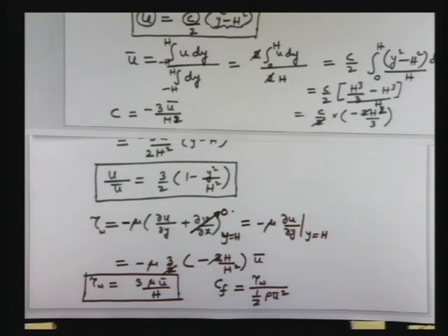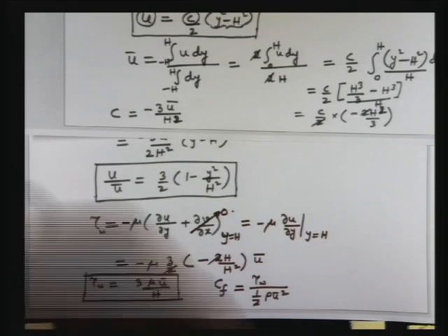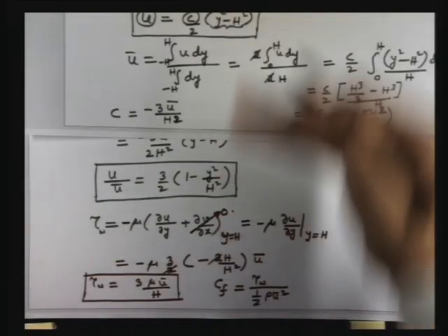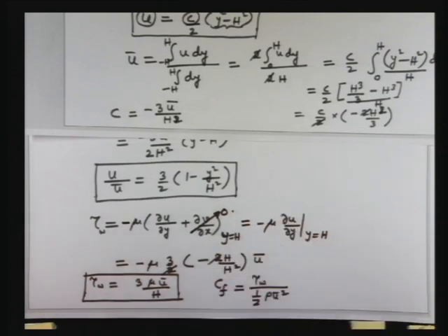So for Hagen-Poiseuille flow, we have given you a tutorial homework. It is just a collection of similar steps, just the governing equations change, not in principle but in form, because there you use the cylindrical coordinate Navier-Stokes equation. Here we have used the Cartesian coordinate Navier-Stokes equation, and there because of the geometry we use the cylindrical coordinate Navier-Stokes equation.